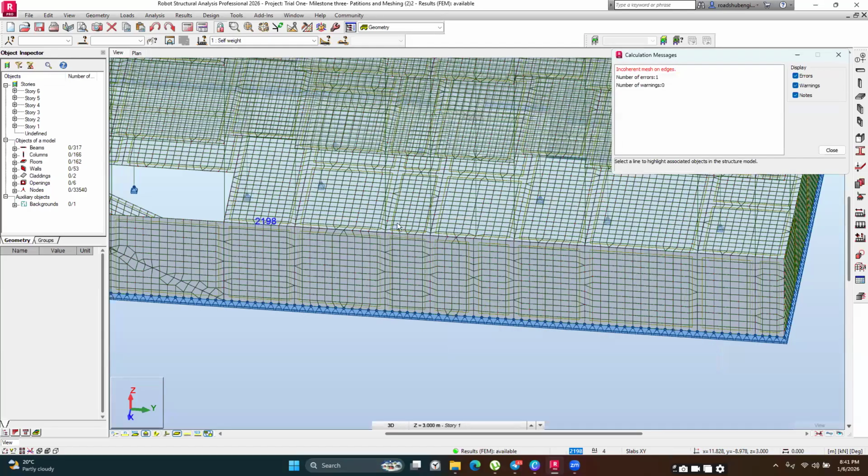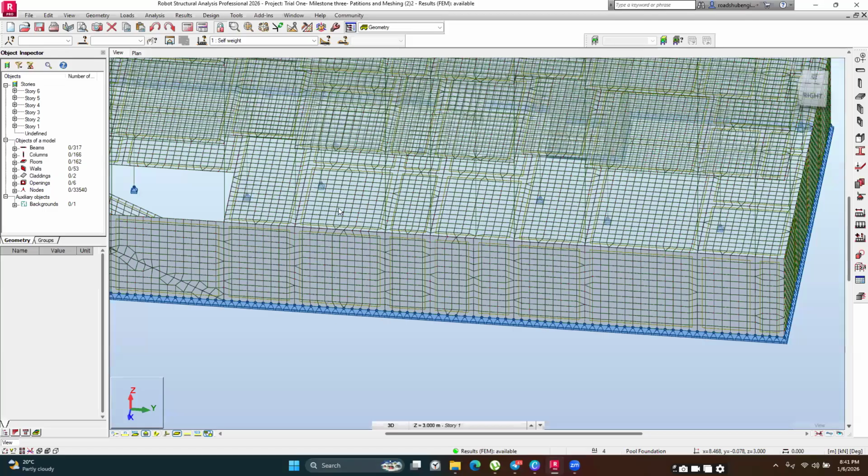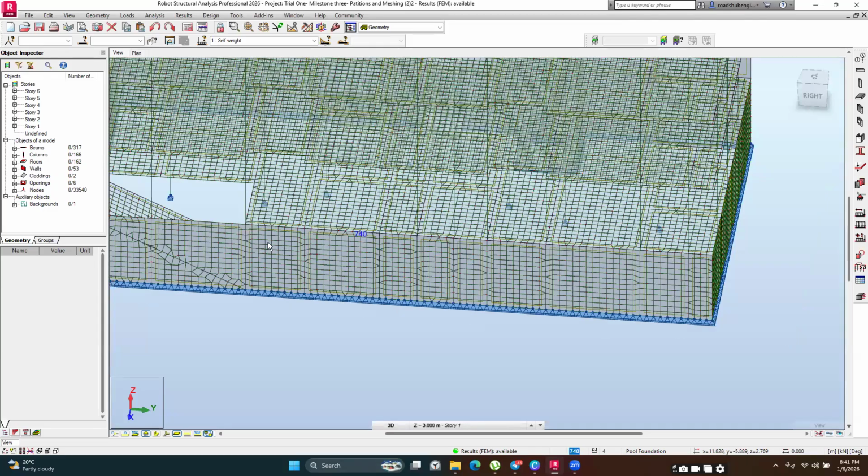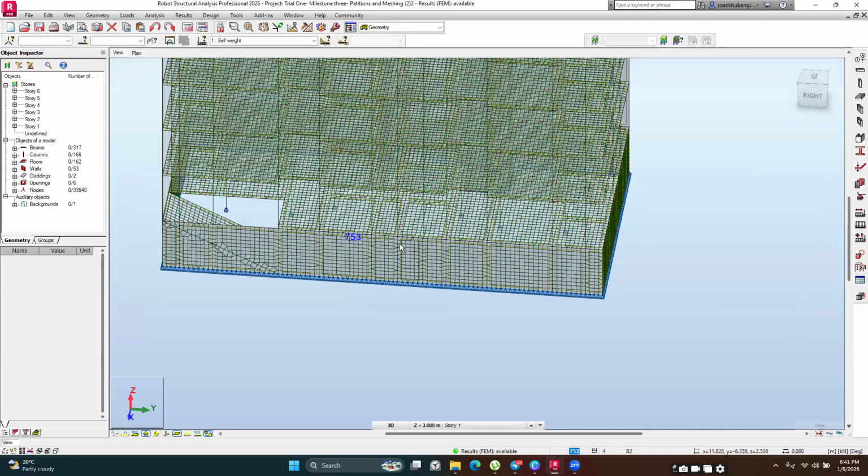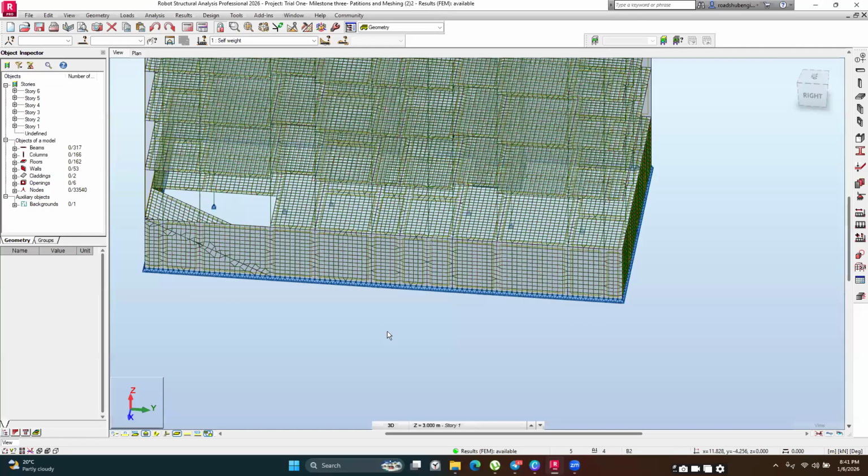The one that I would recommend you have a very good look at is the instability errors. If you have those instability errors, type 1 and type 2 mostly, you may have to redo your modeling. And if you have the separate structure, just redo your mesh, and sometimes it will disappear.